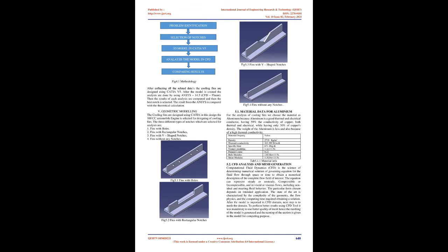by using ANSYS. Air cooling: mostly automobile bikes using direct air cooling, without an intermediate liquid, were built over a long period, beginning with the advent of mass-produced passenger cars and ending with a small and generally unrecognized technical change. Air cooling is a method of dissipating heat. It works by expanding the surface area or increasing the flow of air over the object to be cooled, or both. An example of the former is to add cooling fins to the surface of the object, either by making them integral or by attaching them tightly to the object's surface, to ensure efficient heat transfer.